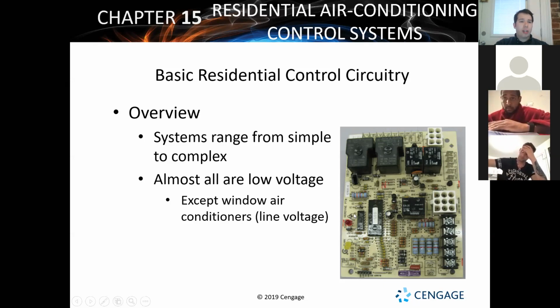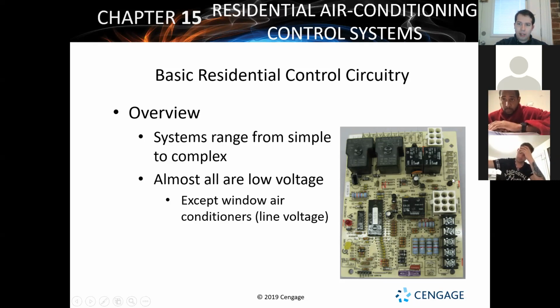And that lets the board know, okay, yes, we can turn on the heating mode, now we can turn on the cooling mode. So as long as 24 volt connections are good, as long as our switches and controls are good, the only other connections we're going to typically see is going to be our 120 or 240 connections. And you're going to see it arranged like this a lot of times, where on this one, you can see right here, there's like 5 connections.